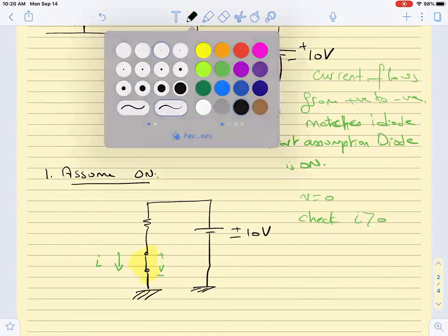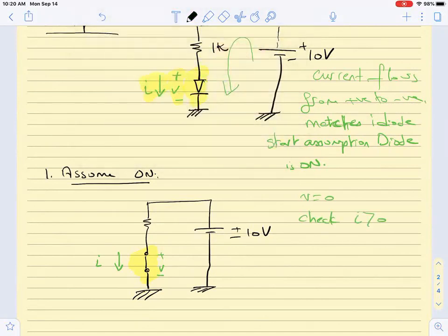How do we solve for this circuit? What do we do? KCL, or KVL, right? Sorry, I was wrong at first. So if we do a Kirchhoff voltage loop, what does the KVL tell us? We said I equals V over R. But if I follow the current going around the loop, I would say minus 10 volts, for a more complex circuit, plus VR equals 0.